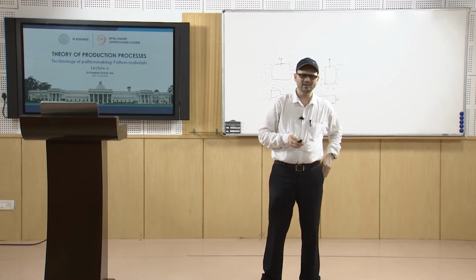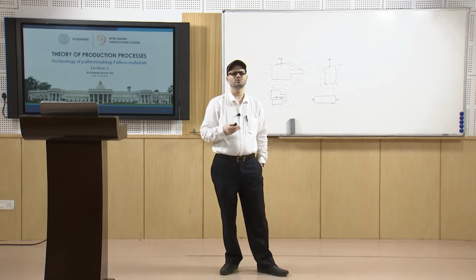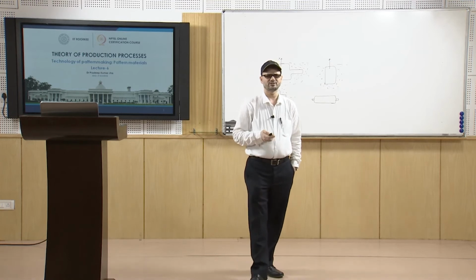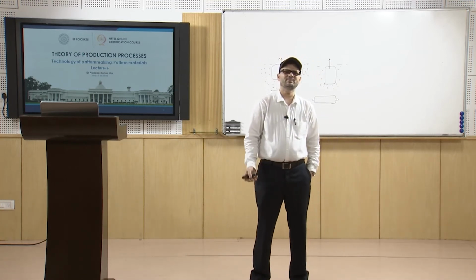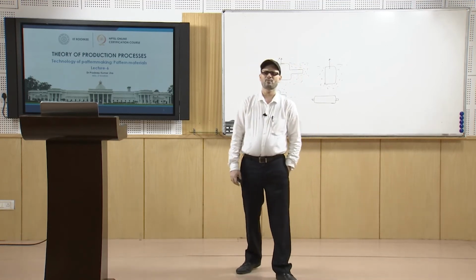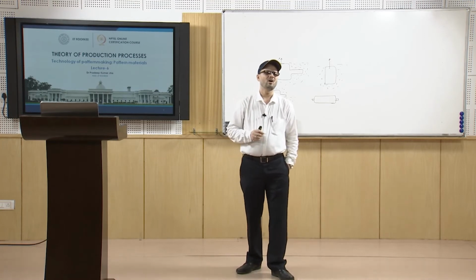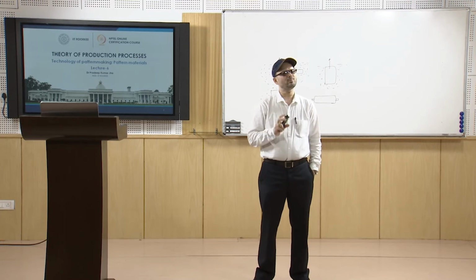So, it is normally advisable when you have to produce small quantities of castings. It has the drawback that it may warp or swell with changes in humidity. If proper treatment is not given to the wood, or if the wood is not of good quality, it may warp or swell with the changes in humidity.